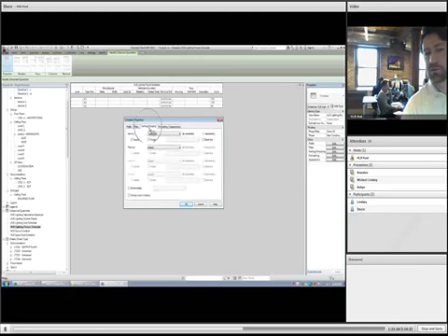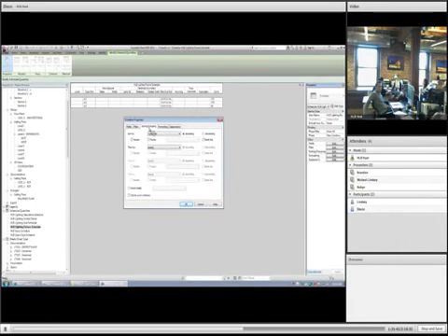We're going to go to sorting grouping here. And this is the thing, you can really start to sort this data however you like. It starts out by doing type mark. We actually would prefer to do it by level and then by type mark. Because first we want the schedule to say, okay, group things by level, only then secondarily do we do the type mark. Type mark 2, you can do a footer.